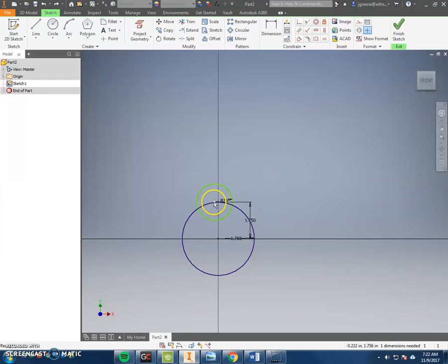That's really important, because I can just move this around, and I don't want this to happen. One of the tools we taught you earlier is that we want these centers to be lined up, and for them to be lined up, that would be a vertical constraint. So I'd select the center of this and the center of this, and they'd be lined up vertically. Kind of looks like a snowman.